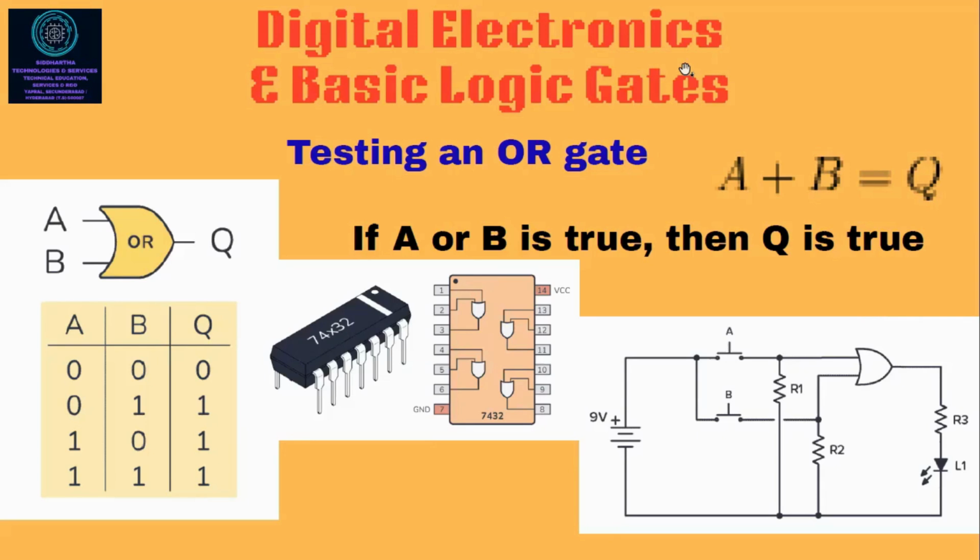So let's start with the testing of the OR gate. Please remember A plus B. The OR gate looks like this, with 3 points: 2 inputs and 1 output. A plus B means whatever signal you give on A and B, according to the truth table, suppose 0, 0, the output Q will be 0.